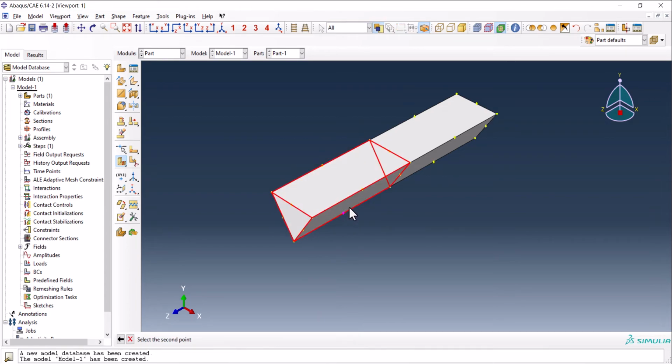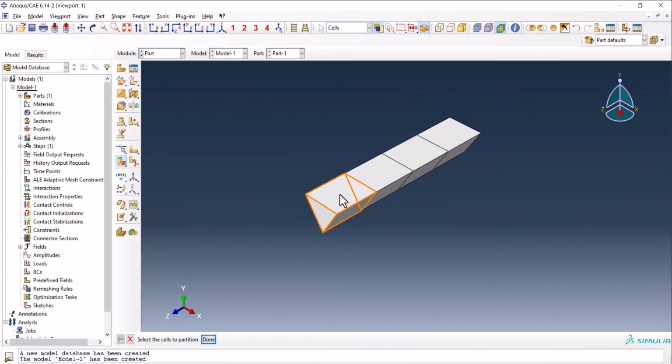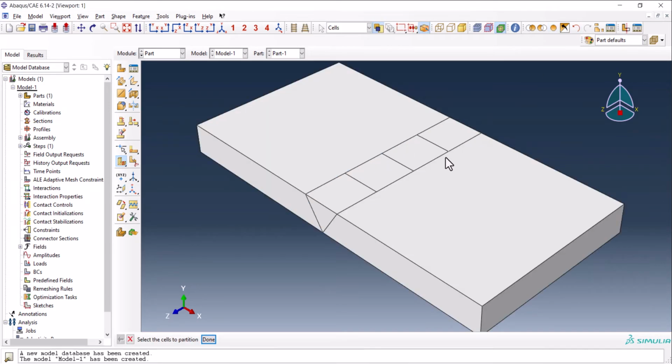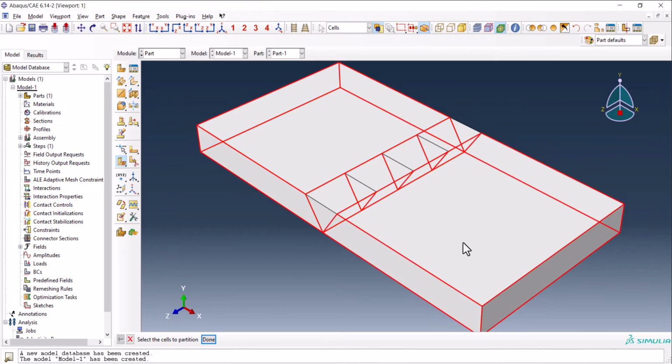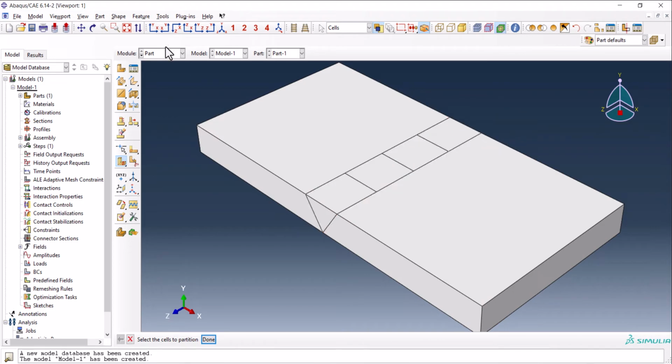like this. So every time I click everything, I click the scroll button of the mouse so that I can create the parts way easier. So I have 4 equal parts here, and by click on replace all I can replace everything. So this is the part, these are the base metals, and here is the weld line. So the part creation is finished.